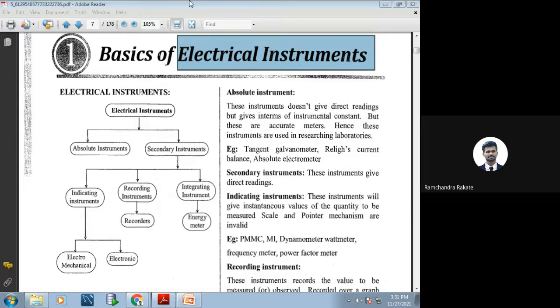Most of the cases when we are working on three phase application, where we are handling 440 volt as a power rating, in that case, don't you think the multimeter that we use for small scale application has more chances of getting short circuit? So to avoid that, we need an instrument that measures the live current without any physical connection. So for that we have the clamp meter. Correct. So this is what is called a clamp meter, which is utilized to measure the current without any physical connection. Correct.